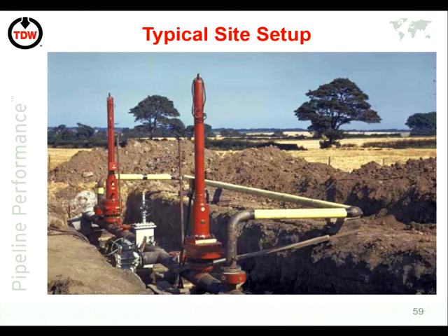Excuse me, does the pressure need to be reduced in the bypass operation? No. If the operating conditions of the pipeline allow that bypass to work at full pipeline pressure, then it will stay at full pipeline pressure. If it's too high, then it may well have to be reduced, and similarly the flow might have to be reduced. But generally, it should be able to operate as is.